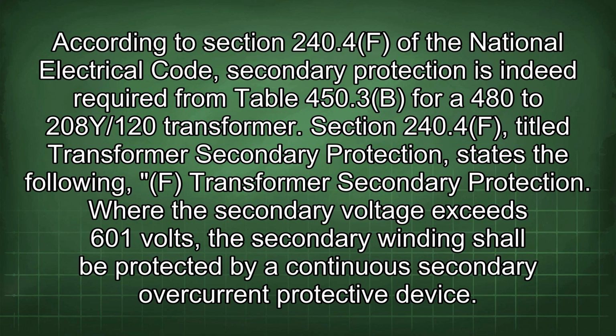According to Section 240.4(F) of the National Electrical Code, secondary protection is indeed required from Table 450.3(B) for a 480 to 208Y/120 transformer.